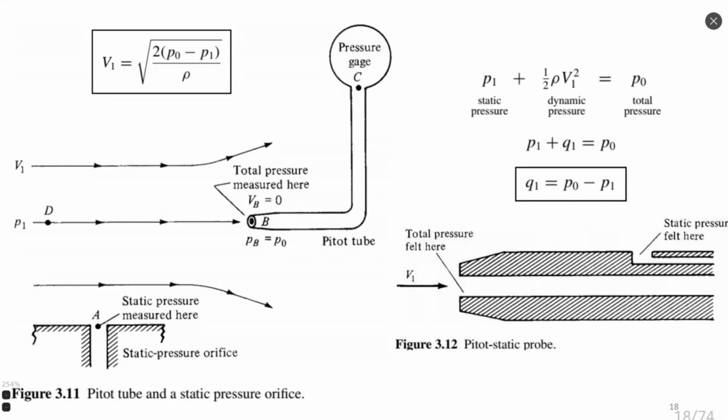One is called total pressure, which is measured by the Pitot tube where flow stops inside, velocity equal to 0 inside such a tube. And so it measures P0 with zero velocity, where all energy is inside pressure, not inside velocity. So we have zero kinetic energy.